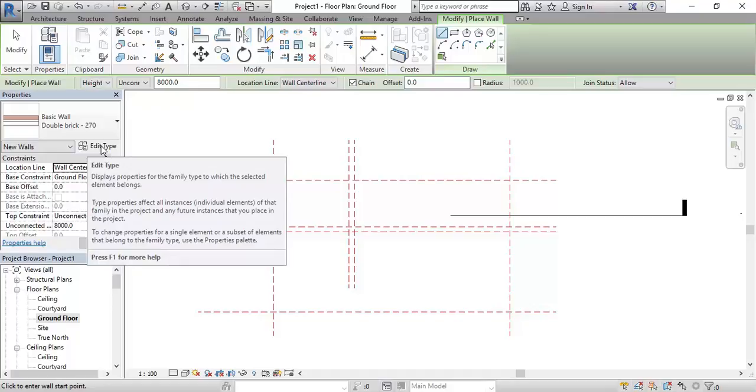Now, in the brief, I've left them grey just so that it's a bit easier for you to read the dimensions. But what colour do you think they should be normally, if it's existing? What hatch do you use for existing elements? You must have seen a floor plan with existing. I know, because I showed you one earlier. Yeah, it's a certain type of hatch you would have all done. Solid. Seen solid black? Okay, so when you see solid black on a drawing, that means it's existing.